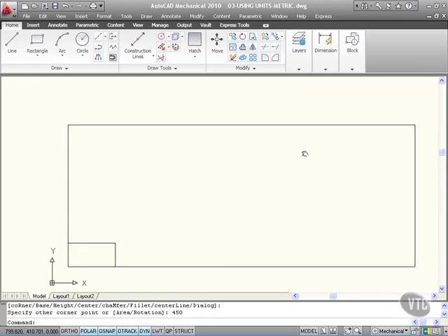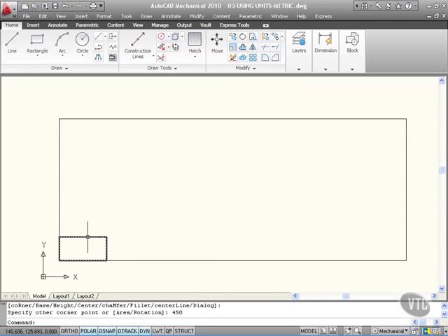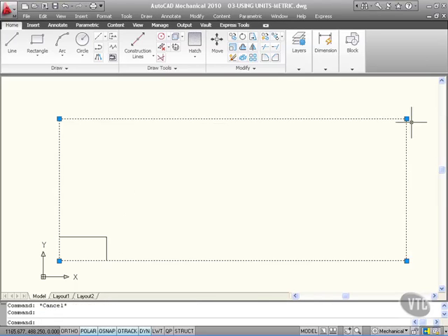If I just move along a little bit now, if I select this rectangle here and hover on that grip there, it's 150 by 75. I'll hit escape to deselect. If I select that rectangle there and hover on that grip there, it's 1100 by 450. So as you can see, there's no distinction between meters and millimeters when you're working using your metric units. Similar process, slightly different display though to imperial units.